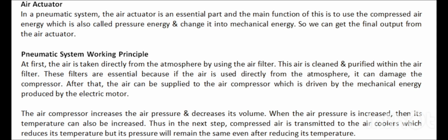We talk about pneumatic system working principle. At first, the air is taken directly from the atmosphere by using the air filter. This air is cleaned and purified within the air filter. These filters are essential because if the air is used directly from the atmosphere, it can damage the compressor.